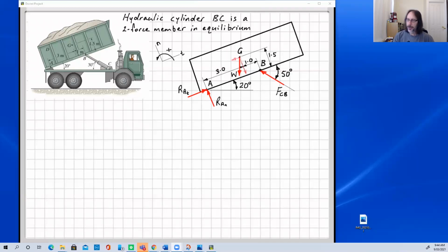So now here I've just broken this weight force up into its component forces in the normal and tangential directions. Okay, so I'll need to do a bit of trigonometry and geometry to work out the correct angles and whether I use sine or cos for this normal component or this tangential direction component. Same with my force here.